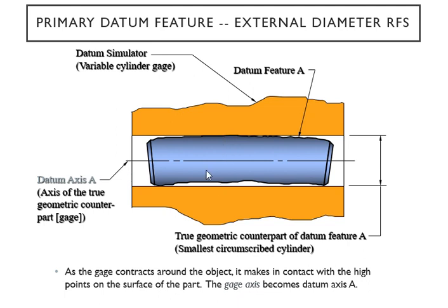Since you have to establish this, we always bring a gauge physically to measure from, because you can't just measure from the surface of the cylinder itself. Our datum axis is right in the center of it, so you need this distance and that distance in order to be able to get that center. Since this blue thing is imperfect or perfect, we don't know, we need to measure it against the gauge. So that's what we're doing.